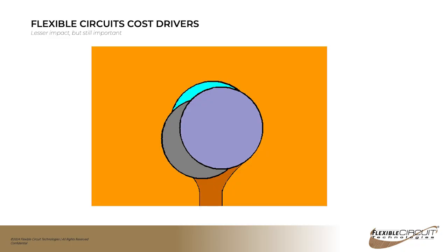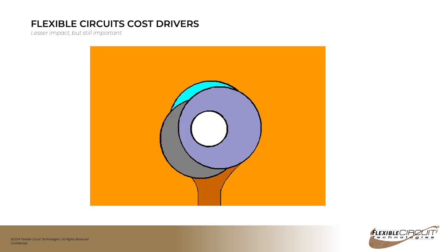Fortunately, most modern manufacturers have optical drills that will allow you to optimize where that hole is drilled and position it in a place where you will have annular ring on all the different layers. However, as things get smaller, sometimes even the optical drills aren't able to put a hole in a place where there's going to be a pad.